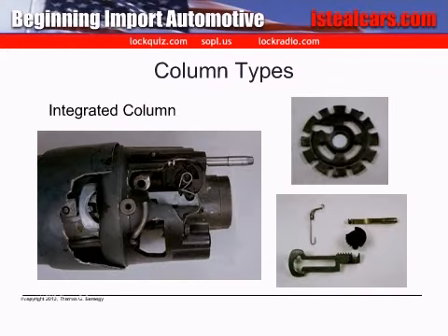Introduced in 1969, the GM Saginaw column stands as one of the most prolific columns of its type. With an increased focus on the security of the vehicle, the Saginaw column moved the ignition lock from the dash to the column and introduced a steering wheel lock. With the ignition lock now located in the column, it was now used to control both the ignition switch's on, start, and off functions, as well as engaging and disengaging the steering wheel lock.